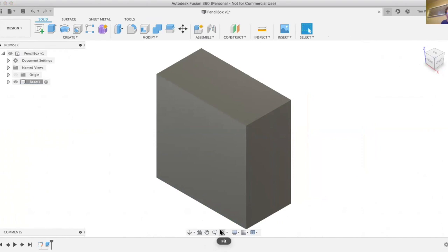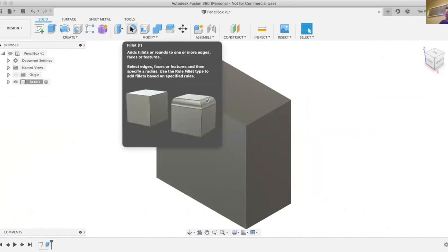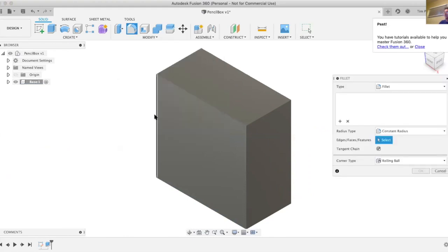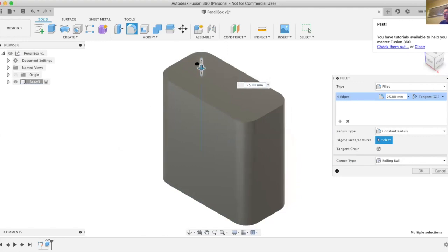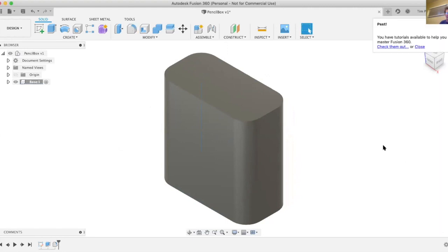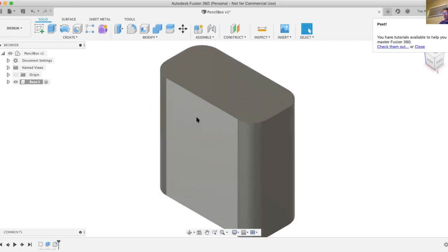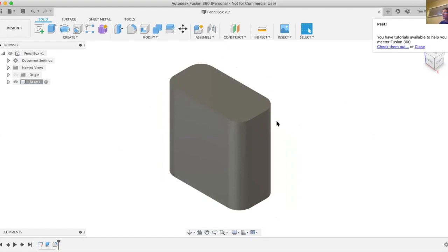Now you remember that the other guy, when he did it, he put fillets in his sketch. And I often don't. What I'll do instead is I'll add the fillet as a solid feature. I'm kind of used to doing it that way, and I find it easier, like I say, to manage features when I break them down a little bit. So there's some fillets. I'm going to say, okay, now this is a solid box that's part of the case. And maybe my height isn't really a good one, but that's irrelevant at this point.